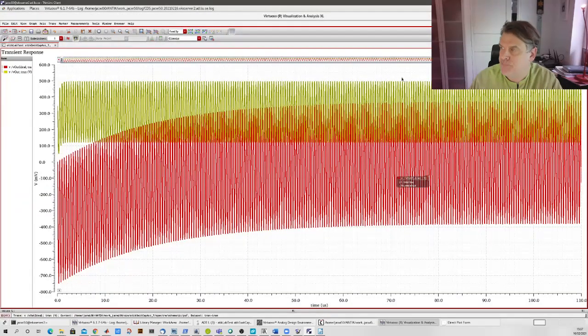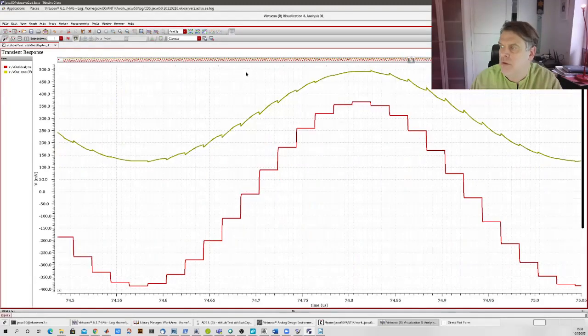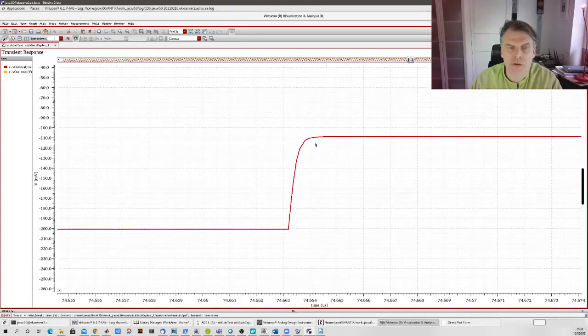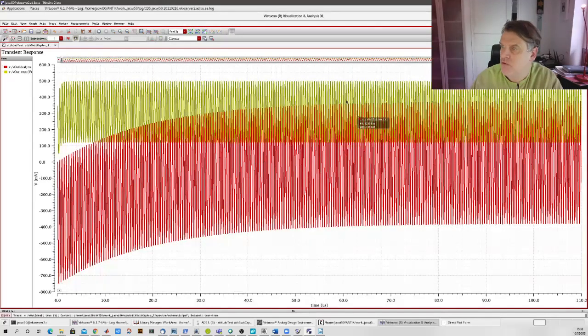Something like this. We can zoom in on different sections, and you see that the ideal one behaves pretty fine. There is a settling behavior. We can see a weak settling behavior going on here, related to this pole that I told you about and the beta. We also see a similar behavior: it seems to hold its value pretty well during the other phase. That's the same thing. We disconnect the switch from the op amp, so it doesn't have that much to do during that phase.